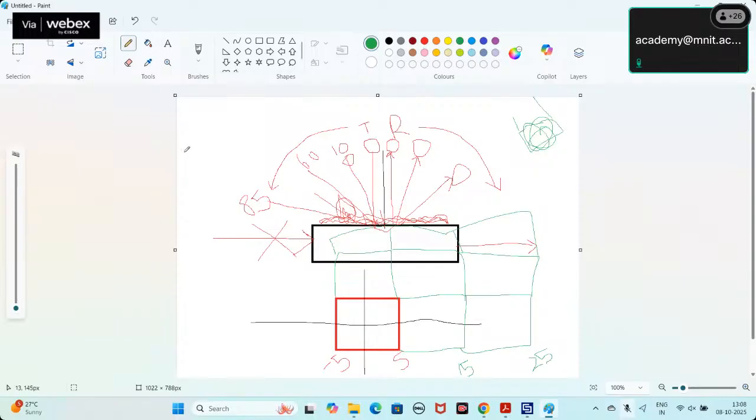In the array, we are making a 3x3 array structure. We have to know this xmin value, xmax value, ymin value and ymax value, and we have to apply a waveguide port on the top and the bottom of this side.